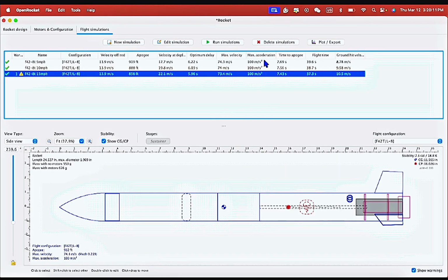And we have this. It's going to go even lower, but basically you can set your own simulations to know what is the optimal mass or like coefficient, center of gravity you want to set for your rocket or stability for this specific height. And this is a flight time right here.